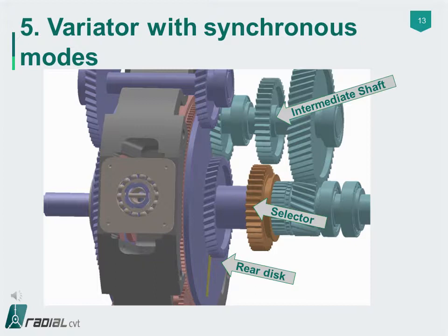The animation presented the addition of a minimal number of components to the Gen 2 radial CVT variator in order to generate 3 synchronous mode transmissions with a ratio range of 9 and beyond. The ratio range of 9 is chosen for simplicity's sake, since with a ratio range of 3 in the variator, a ratio range of 3 squared, equal to 9, is generated with a dual mode system. For example, a variator ratio range of 3.31 will result in an 11 ratio range.